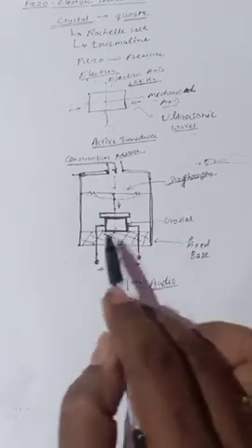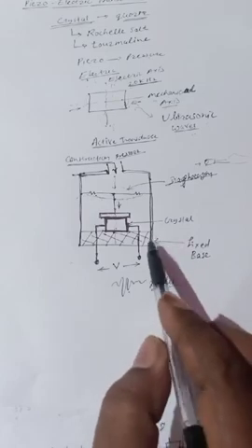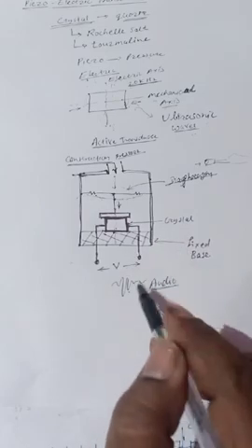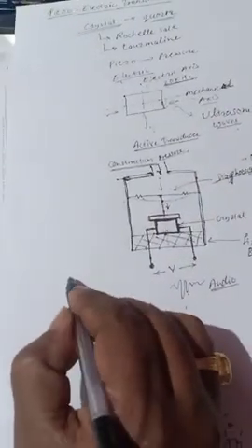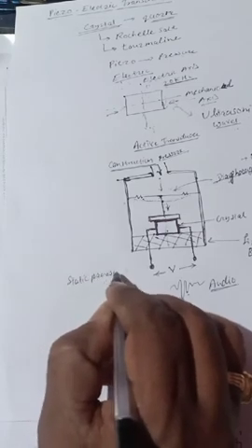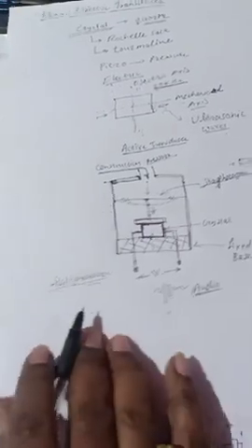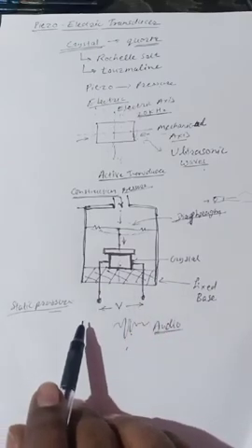Okay, so it has a large temperature range, but it has one disadvantage: it cannot measure a static pressure. Static pressure cannot be measured by this transducer.